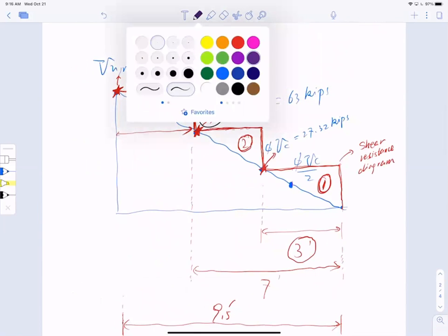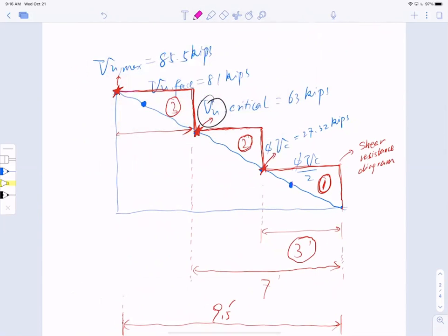You can choose more sophisticated design. For instance, I'm going to use this color. So for instance, you can do this every step, right? You can do this every step. Now you have more precision, and you have saved more materials, supposedly. But remember, when you have more segments, it's going to increase your construction cost. Imagine how the field engineer will curse your name when they see this design, because they have to design 4 different zones and ask their field technicians to put down 4 different spacings. That's quite costly.